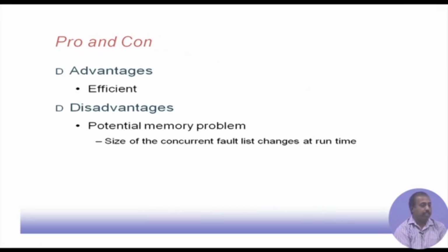Advantage, this is efficient definitely, but the disadvantage is the memory problem, because in concurrent fault simulation I need to remember a number of bad gates for every good gate. So, I have to remember more gates, which means more amount of memory and runtime complexity.